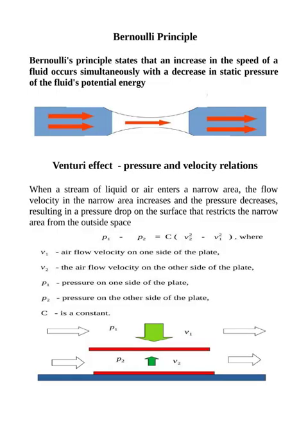Bernoulli principle. Bernoulli's law establishes the relationship between the velocity of a stationary fluid flow and its pressure. According to this law, if the fluid pressure increases along the flow line, the flow velocity decreases, and vice versa. Thus, when the airflow passes through the narrowed part of the pipe, the flow rate increases. This can be used for a wind turbine placed in a pipe.